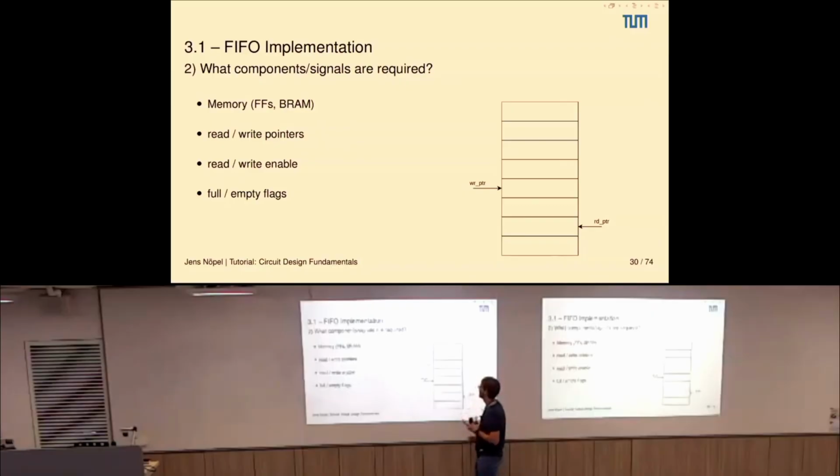All right. So now there's just one packet left. So it reads out this one. The write pointer is already pointing here, right? And it increments this one as well. And now you see, both the write and the read pointers are pointing to the same location. So now I know, if they are exactly the same, then my FIFO is empty, and I accordingly set the empty flag. So that's how this works in theory.